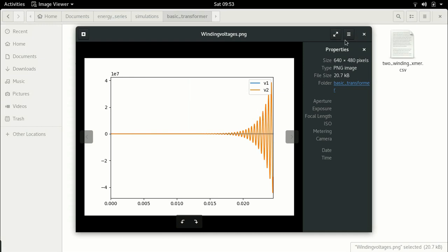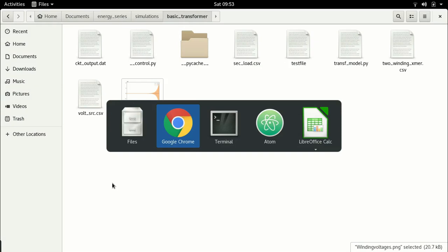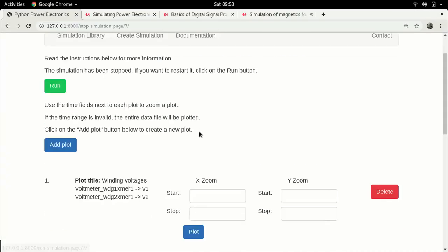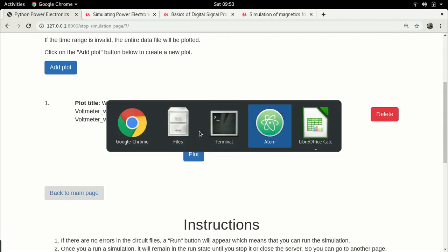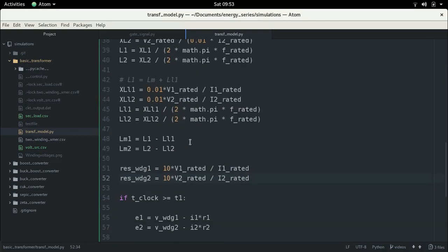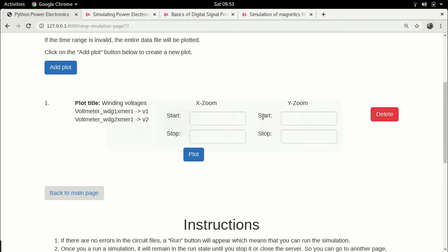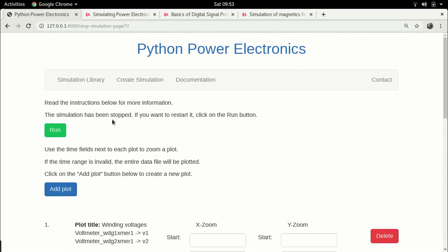Now, these instability problems can be a little difficult to solve, but like I said, one simple way to do this is just to increase your resistance just a little, right? So I would just increase this to 100. And let's run the simulation again.